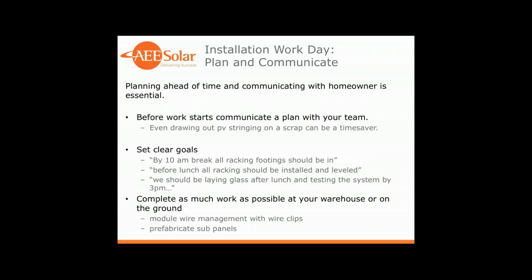And in different cases, depending on your hardware, I find that some of the most effective installation crews and teams out there are able to do much of the more tedious items right on the ground. That means in the warehouse, they'll pull up the modules and slap in a bunch of those wireframe clips on the side of the modules and get the cables so that just barely a couple inches of wire can be pulled off of it.